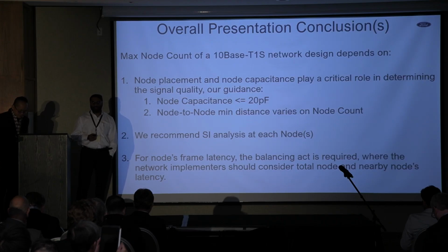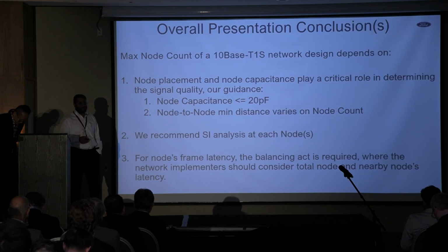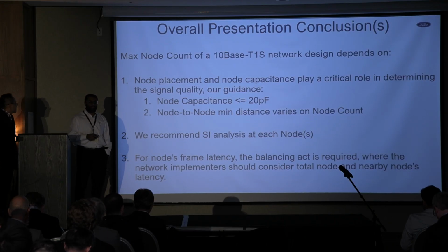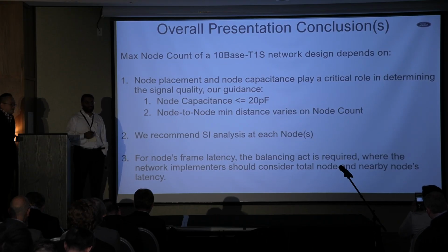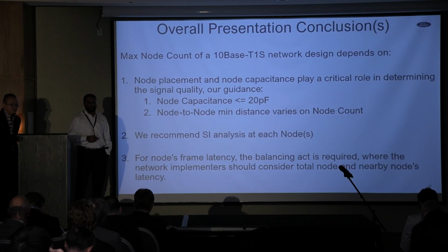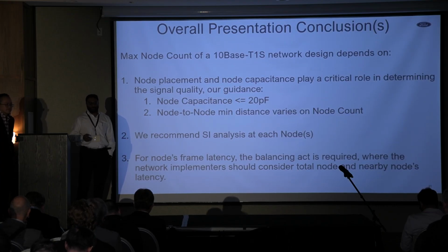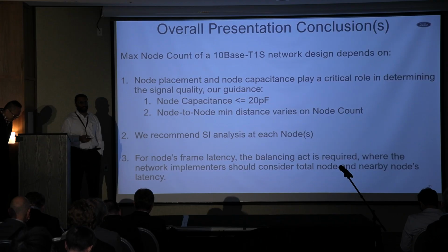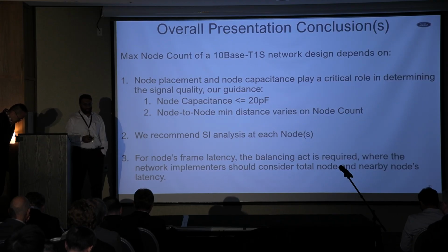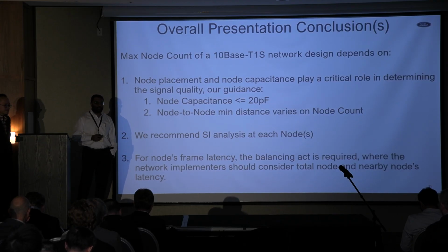What we also definitely recommend is to have signal integrity testing on the final topology at various points in the topology, just to make sure that the signal is behaving within the specified parameters. So definitely, either through simulations or through actual measurements, we recommend running the signal integrity analysis at different points